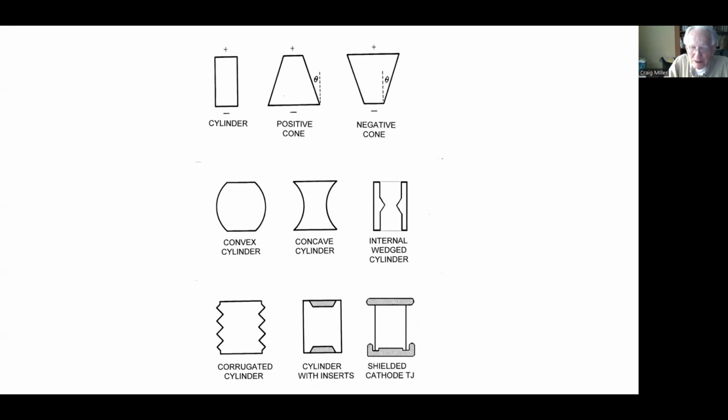It's a trade-off. Five short insulators with the same total length will have a higher hold-off voltage than one long insulator, because of the very short insulators' proportional length. As it becomes longer, it becomes less than proportional, and for the longest, proportional to the square root of the length. But it also turns out the more insulators you have, the more triple junctions and more weak points.